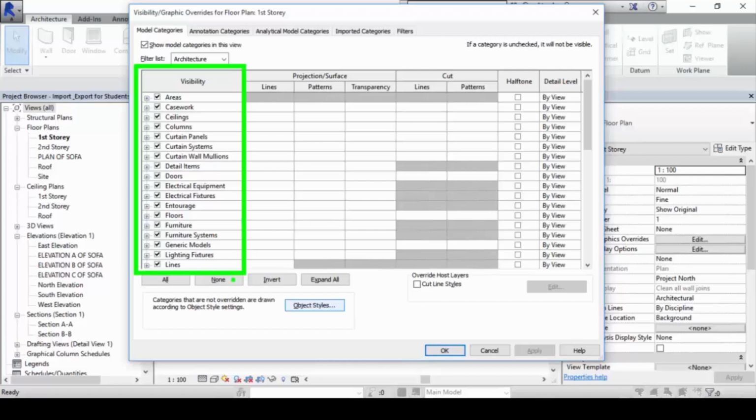Now the Revit project file is essentially a compilation file that holds all the families. And these are the family categories all here. They are broken into three things: the model category, the annotation category, and the import categories in general. Alright? And if you look across here, down here, you will see this table on projection. And this part, you will see cut.